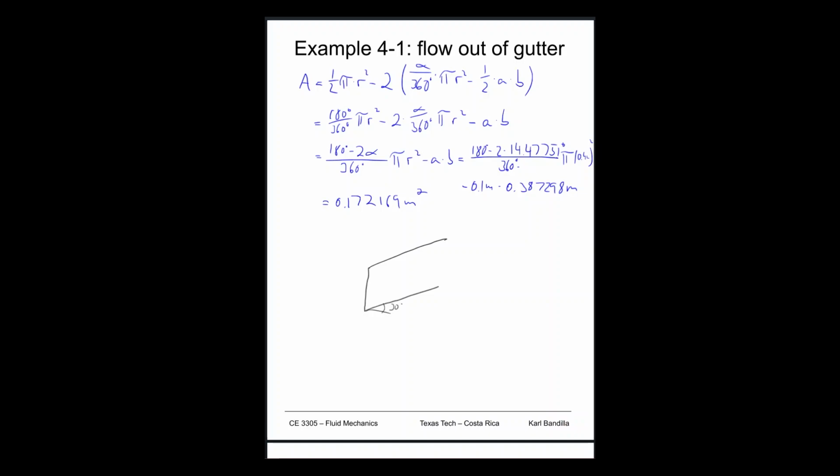We know that our water is coming out the same as the pipe, but the vector of the area is perpendicular to the cross section, so it's at a different angle. So we have 30 degrees here as well, which means if we want to calculate Q, we'll have to take that into account.